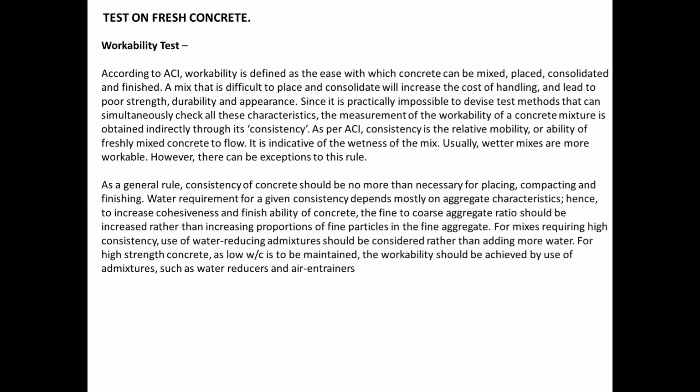Water requirement for a given consistency depends mostly on aggregate characteristics. To increase cohesiveness and finishability of concrete, the fine to coarse aggregate ratio should be increased rather than increasing the proportion of fine particles in the fine aggregate. For mixes requiring high consistency, use of water-reducing admixtures should be considered rather than adding more water. For high-strength concrete, as a low water-cement ratio is to be maintained, the workability should be achieved by use of admixtures such as water reducers and air entrainers.